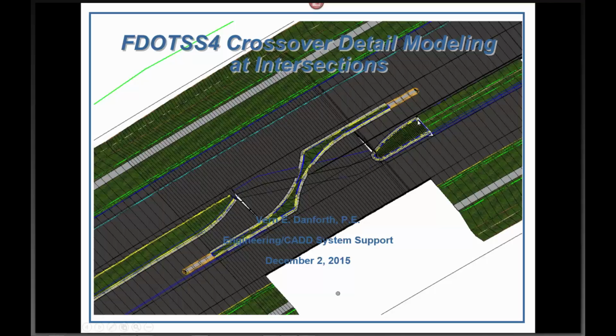You can also put a parametric constraint on the actual component itself to drop that if you want to flare it down to 0. And so that's essentially what you're doing. You're just placing linear templates around these elements, both sides. You place a linear template along one side of your traffic separator and use the traffic separator component, and then just use a point control on one side. Do the same thing as far as the nose. You can use a civil cell for that.